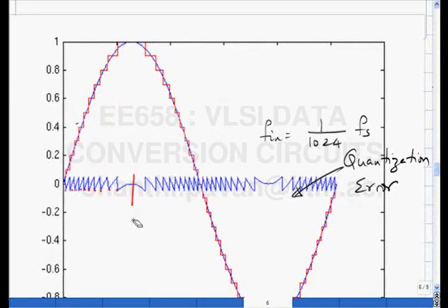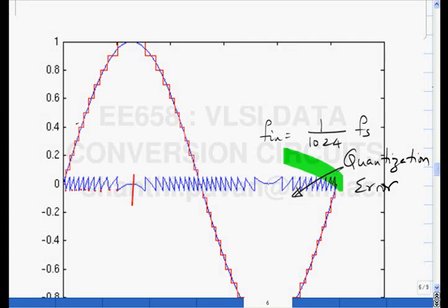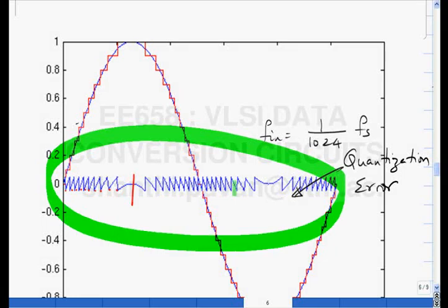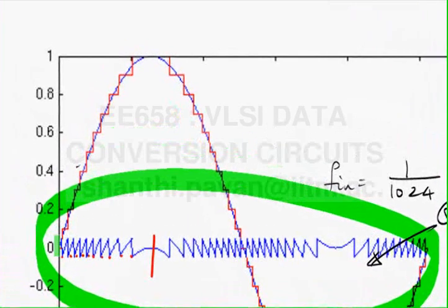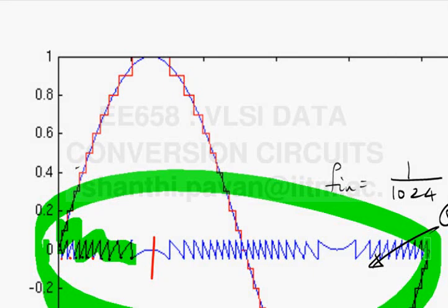Okay, when you expand a frequency modulated sine wave in a Fourier series, what do you get? Basically, if you take an FM modulated sine wave and do a Fourier analysis on it, the Fourier coefficients will all be Bessel functions. So it turns out that, not surprisingly, if you compute all the Fourier coefficients of this quantization noise, you can express them in a Bessel series. This is a general truth, but the unscientific way of describing this waveform is that it's periodically periodic. There's local periodicity and there's certainly overall periodicity with this large period.